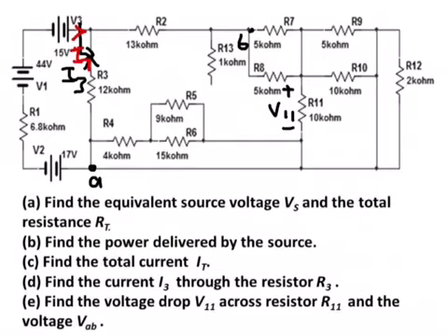Now the circuit as it stands looks a little bit scary, but it's not really that difficult because there are many simplifications that you can make before you do any calculations. So we do these simplifications, we redraw the circuit, and the circuit will look way simpler. Let's see. We can see that these two resistances are in parallel and they are in series with this one. So this branch will give me one equivalent resistance.